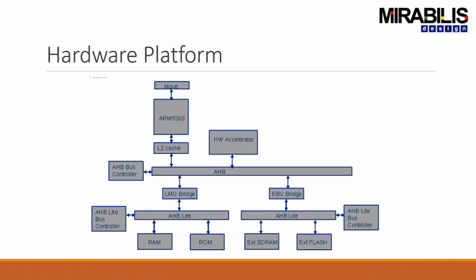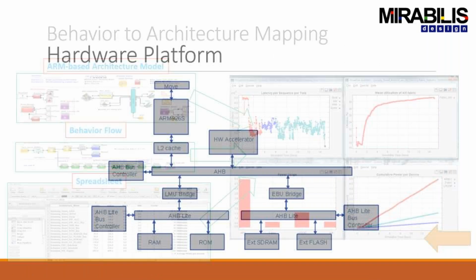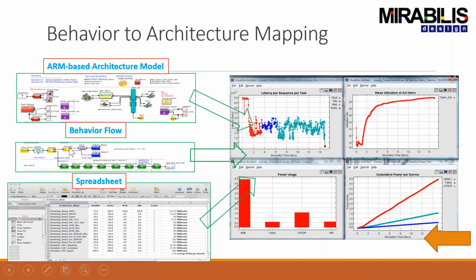I've got processors, buses, memories, I/O devices, bridges, all of this kind of thing, and then assemble up a system, define a behavior, define all my power, and then be able to run simulations by combining the three and looking at what the utilizations are, what the cumulative power is, what the latency was for different types of tasks, being able to analyze all of those to go back and start modifying the hardware architecture.